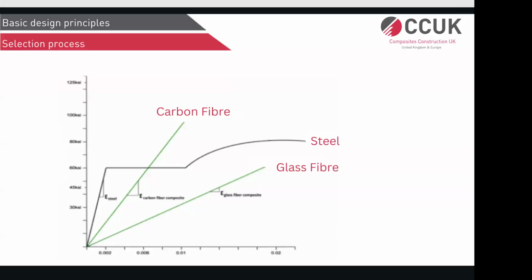Generally what people do is that they approach the FRP design similar to how they approach the steel design. So in steel design, you take the yield stress of the steel and the force you need to carry, divide that force by the stress, and that will give you the area of steel required. But in FRP design, it's slightly different. How you design FRP is basically you take the modulus of material from the datasheet and the thickness of material. Those are the only two things you use from the datasheet. Then you limit the strain depending on the guideline you're following. So if you're using ACI for a particular instance, it might be a little lenient, whereas TR55 could be conservative or vice versa.